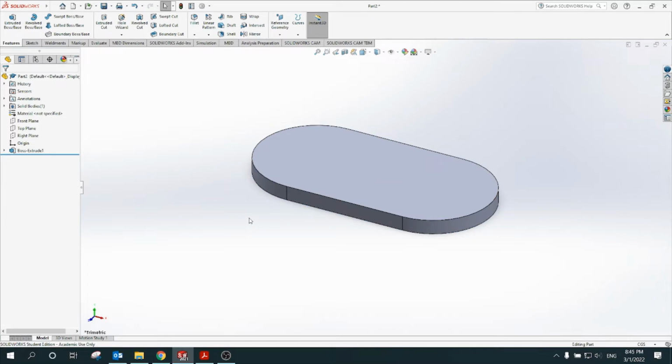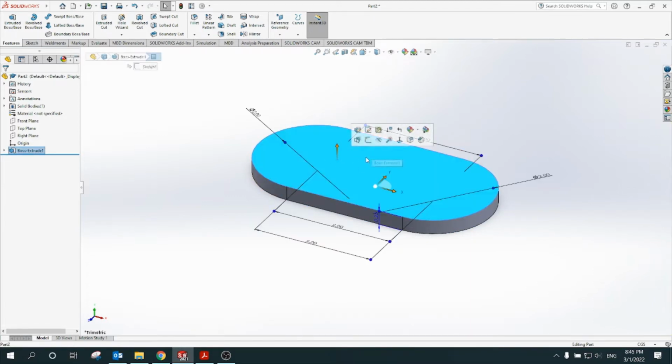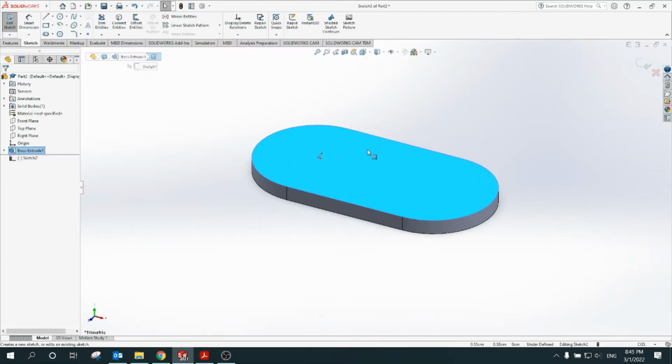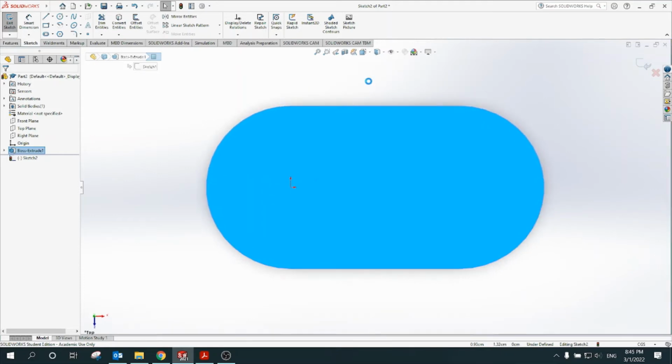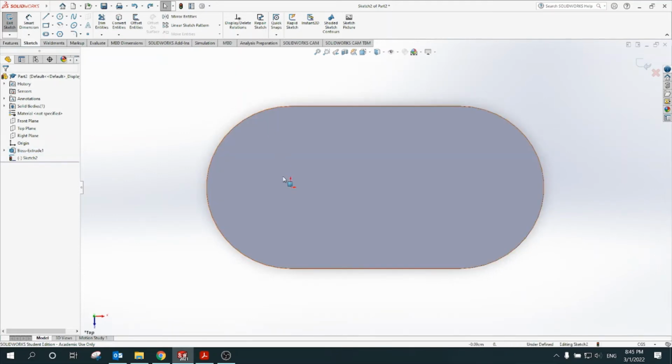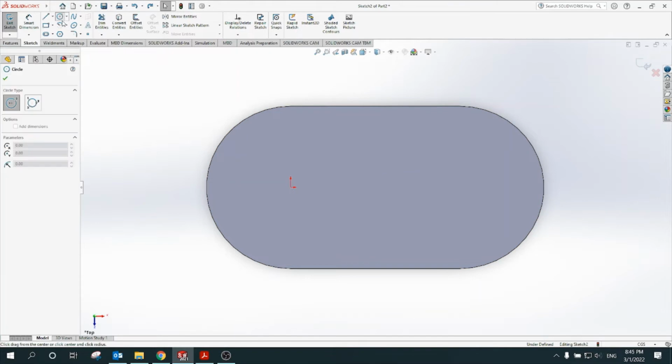Now for segment number 2, it's made on this top plane, so I'll just click on the surface and create new sketch, and I can say show me the top view. Remember that I can use the origin, or I can use all features given from the previous sketch I did earlier. So when I create circle, I can say it's in the origin.